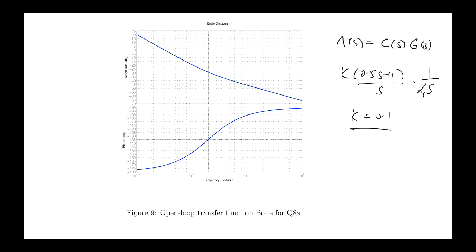And we need to choose the gain such that this becomes the crossover frequency. So we've got to choose a gain that's consistent with 30 dB, so it's multiplying by more than 10. What we're seeing here is a way to use the information in a Bode plot to make a design decision.